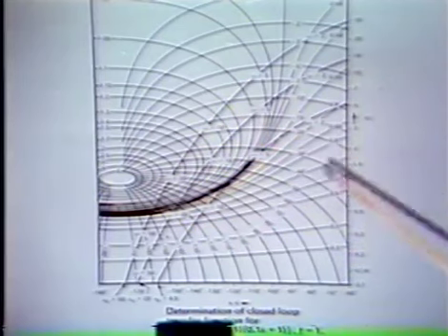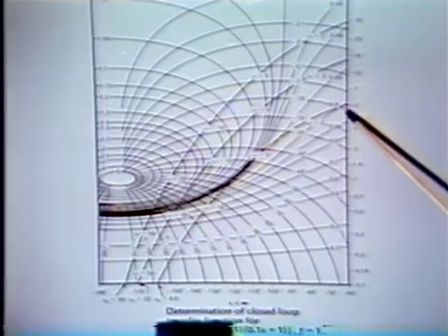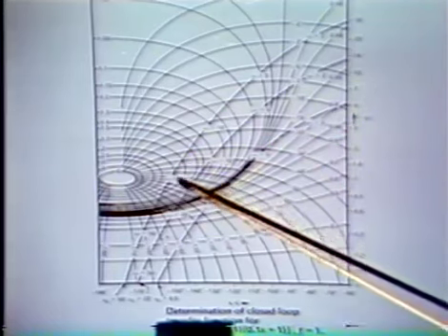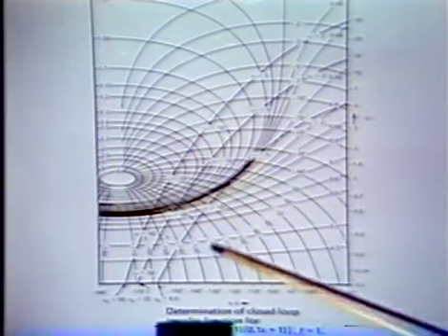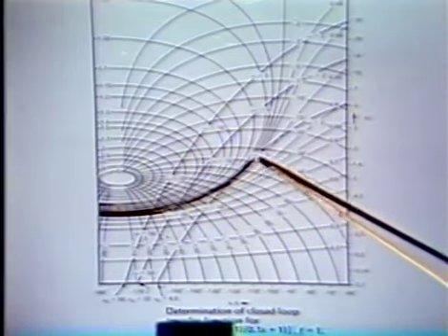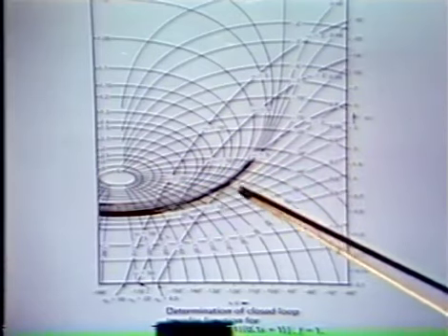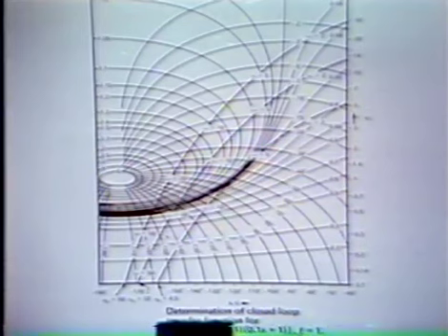And what we're able to do then is determine the closed loop gain of our system by simply going ahead and looking at the magnitude of G over 1 plus G in these coordinates, and if we cared to, the angle for various values of omega and a specific value of A0. And we can see how that works.